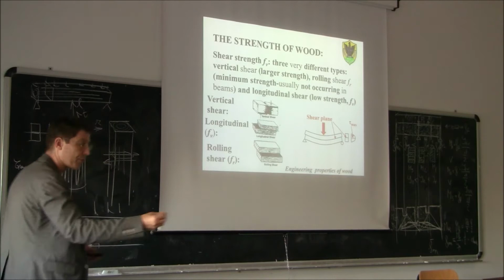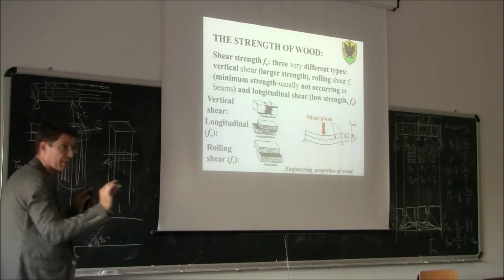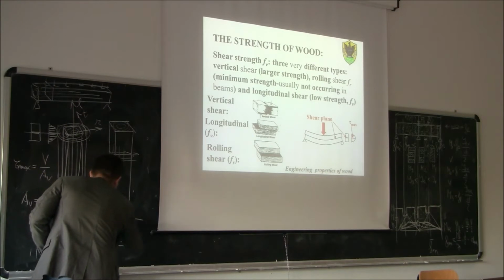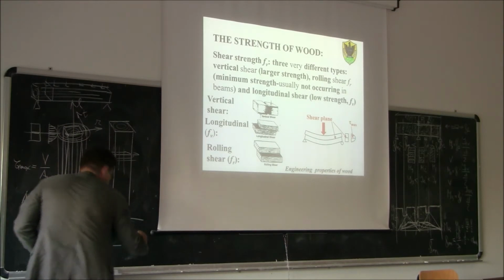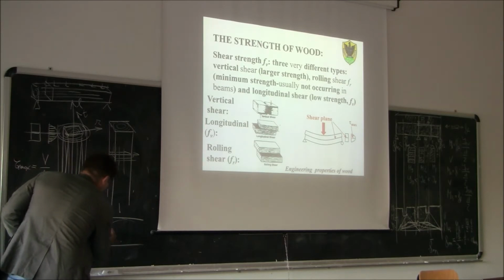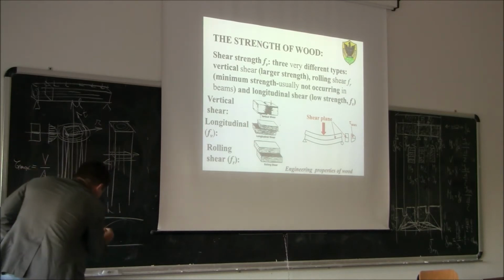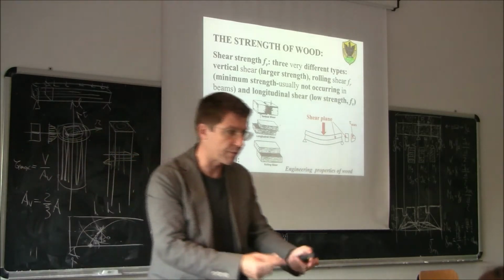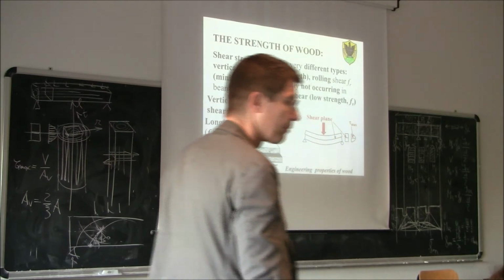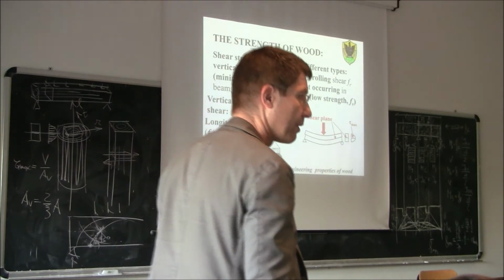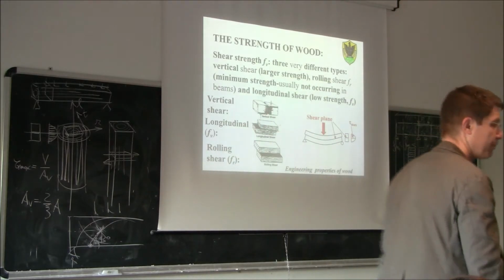Because you can find out, if you remember, if you have a homogeneous isotropic material, there are some isostatic lines, compression, isostatic, and tension, and so on. If you remember well, around the neutral axis, more or less, you have an inclination of the main direction of 45 degrees. Now, in theory, how would you expect the shear crack to form?